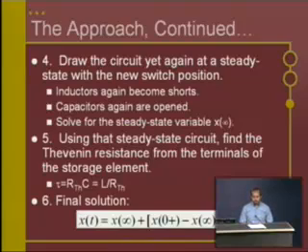And so inductors short out again, the capacitors open up again, and we solve for the final steady state version of that parameter.